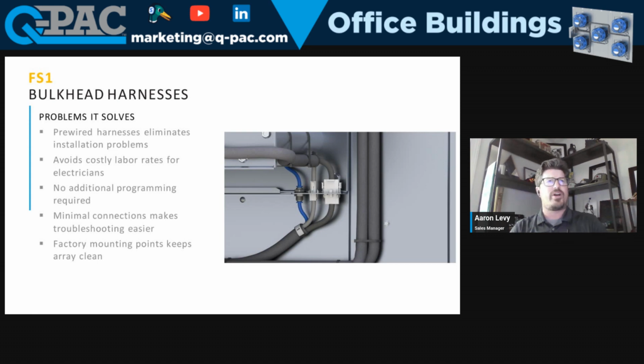And when we talked about the wiring harnesses, every fan will come with the same connection points. And then you've got wiring that comes back that we provide. That'll be labeled fans 1, 2, however many fans there are, and they'll go to their dedicated wire routing. But we take all that into account from the quick connect box to the fans themselves. They're just Molex plugs. They are not weather sealed. Typically, if you're having any kind of humidity issues or outdoor air or moisture problems, silicone and dielectric grease could be a really good saver to make sure you don't run across any shorts.